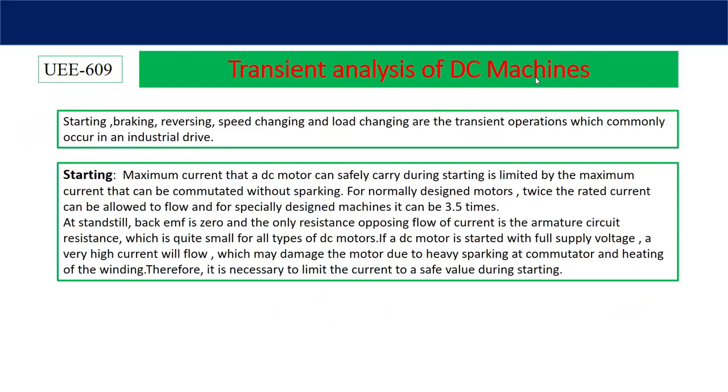The transient analysis of DC machines: starting, braking, reversing, speed changing and load changing are the transient operations generally seen in case of DC motor drives as well as induction drives, or you can say the complete drive system. Now at the time of starting, the motor draws a large amount of current from the source. Now that current is to be limited,